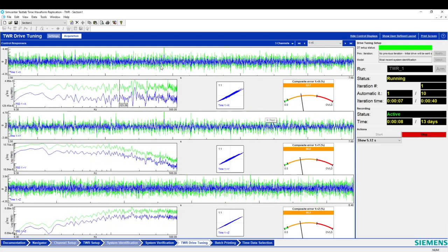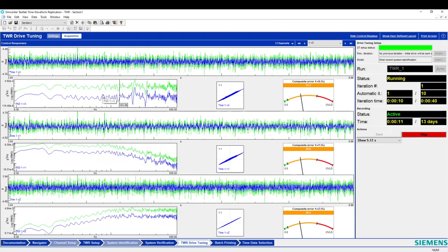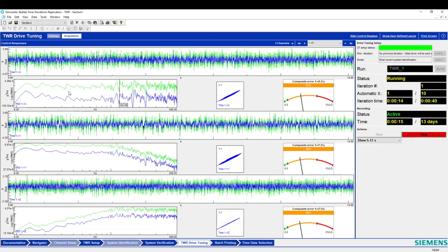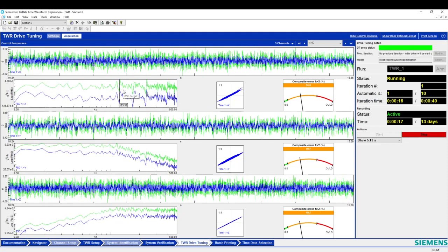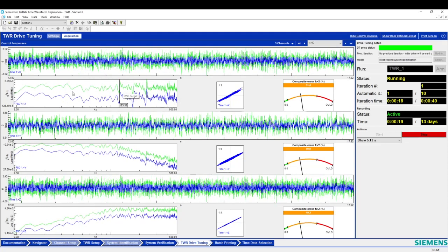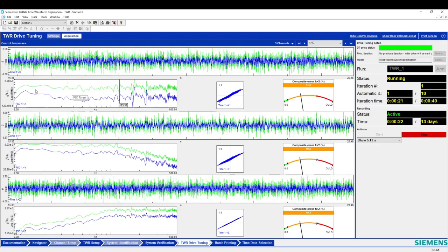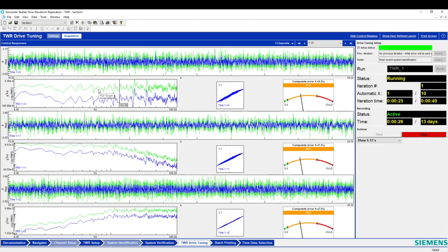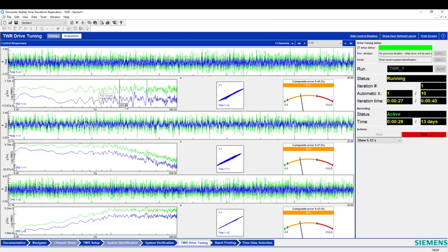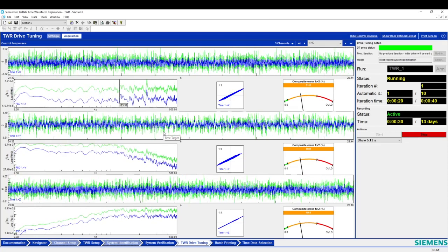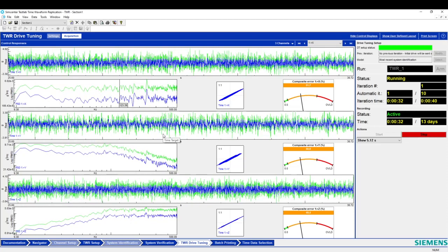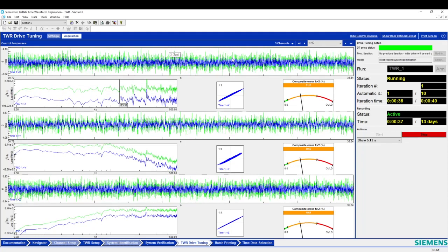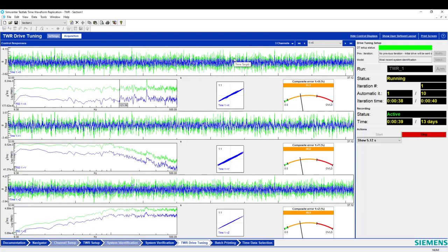As explained before, the test started from 50% of the full level, as you can see here in the PSD plot. The green line is our full level target. The blue one instead is the measure. Here you can see, of course, the time domain, the time history.